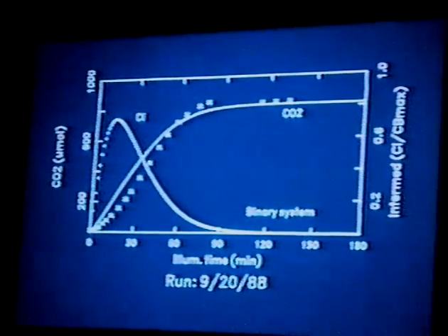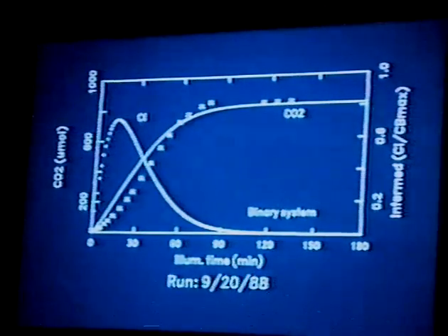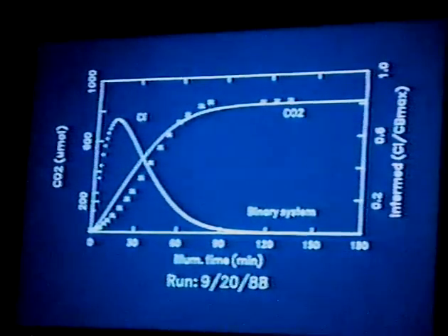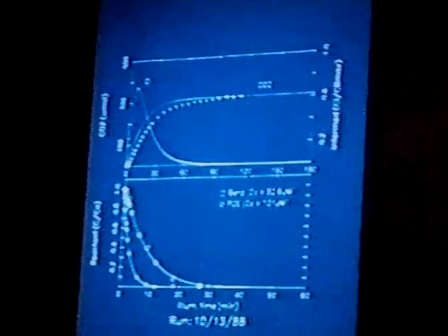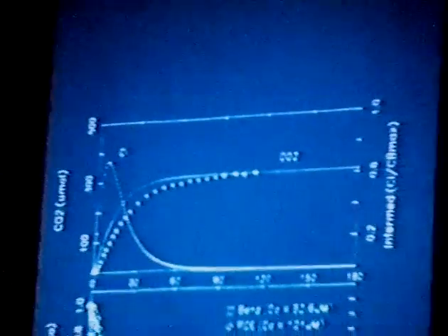We see we have quite a good correlation, except down in this very low time region. There are a couple of reasons that could cause that. One, there's a slight probe lag, well, a significant probe lag actually in the low time region. However, that factor is probably not too great. It's more likely that since benzene is proceeding through a number of intermediates rather than just one, we're not weighting the initial time region properly. Another set of data here showing the CO2 stacked on top of the degradation rate. We see again we have a good correlation between the experimental and predicted degradation.